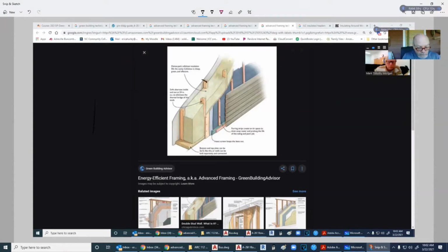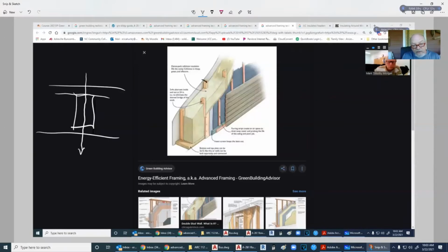When we have a regular wall, we have to think about heat conducting through the stud, right? So this is completely open so that we don't have any of the inside touching the outside except for the top and bottom plates. But look at this, top and bottom plates can be as big as a 2x12. Have you priced a 2x12 lately? The damn 2x4s are 7 something. So this is serious. Basically that puts insulation between the walls and the studs, so there's no transfer of heat through there at all.